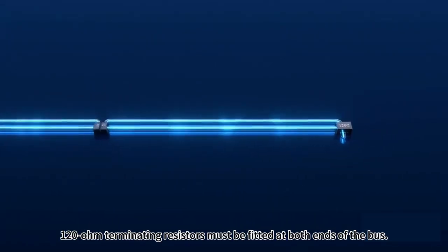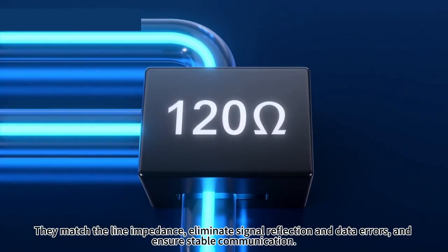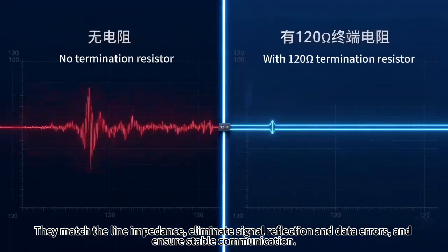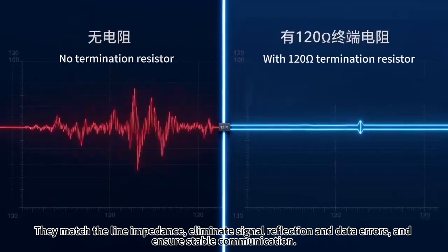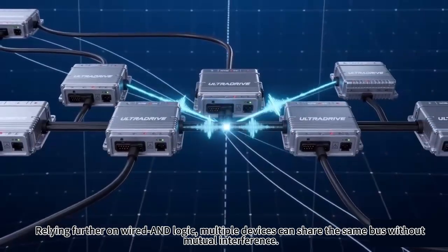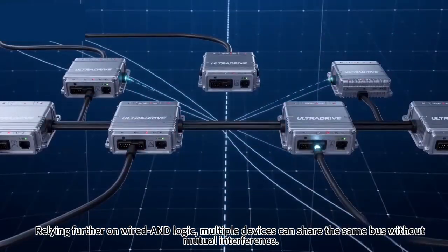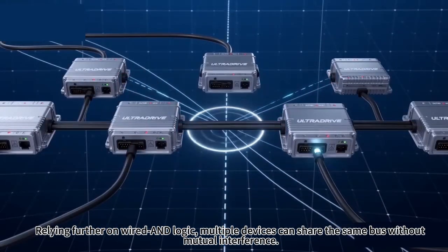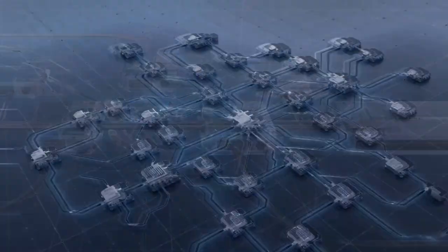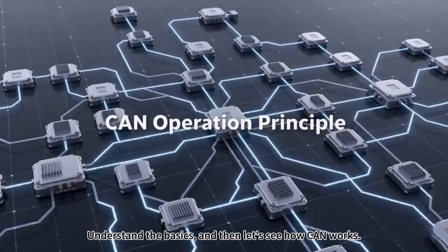120 ohm terminating resistors must be fitted at both ends of the bus. They match the line impedance, eliminate signal reflection and data errors, and ensure stable communication. Relying further on wired AND logic, multiple devices can share the same bus without mutual interference. Understand the basics, and then let's see how CAN works.